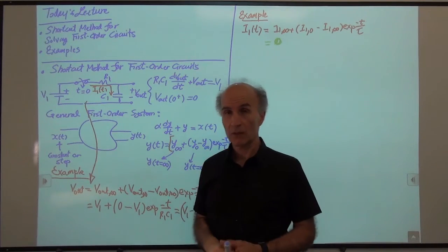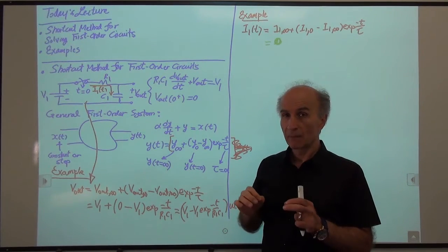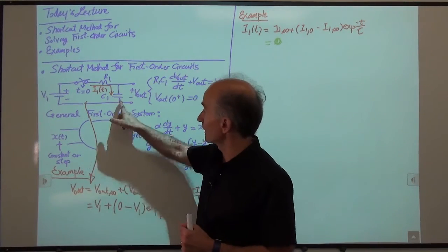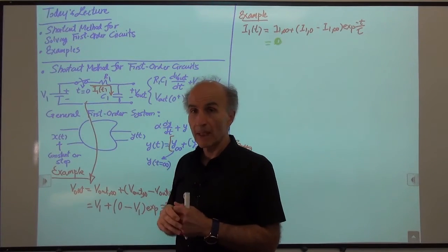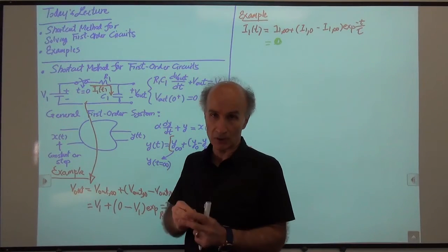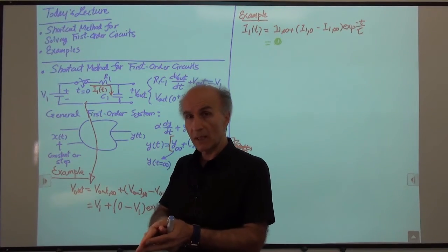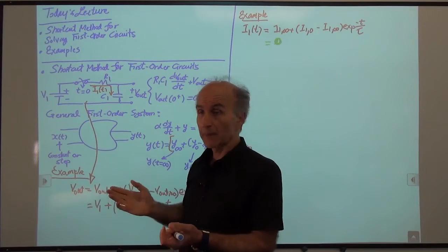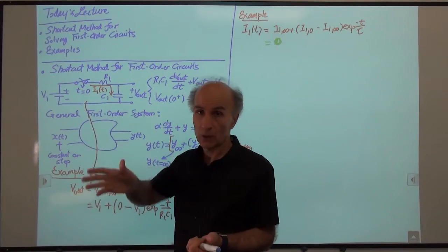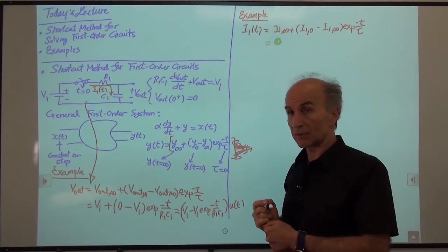There's another perspective that I can also see from what we saw last time. We know that the voltage on the capacitor eventually reaches a constant value, right? This capacitor charges up to the battery voltage. When the voltage on the capacitor is constant, the current through the capacitor is 0, right? C dV over dt. If the current through the capacitor is 0, then the capacitor acts as an open circuit, right? So if the capacitor is an open circuit, there's no current here, this voltage and this voltage are equal. So that's another way of thinking about why the current through the resistor has to be 0.